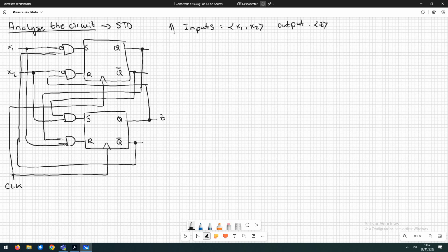And the state variables: I told you that each memory element is going to store a state variable. Here we have the memory elements given in a generic way. We can modify them slightly to have our specific state variable. For the kind of memory element, we can see that they are SR bistables.